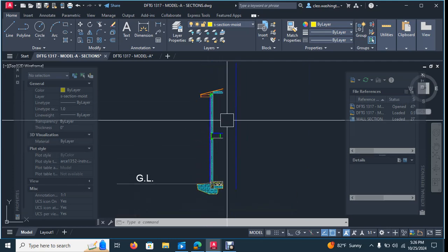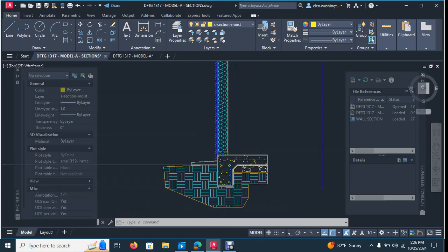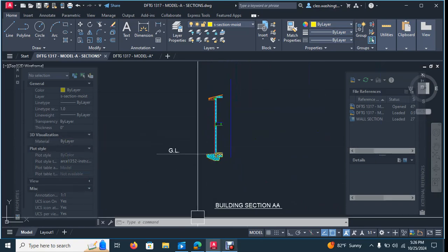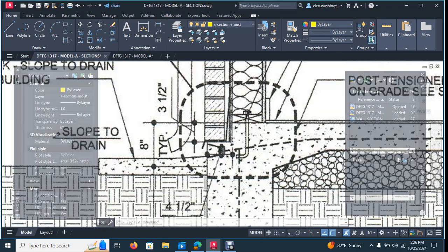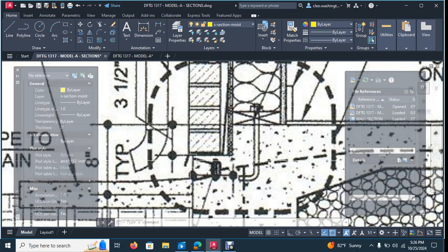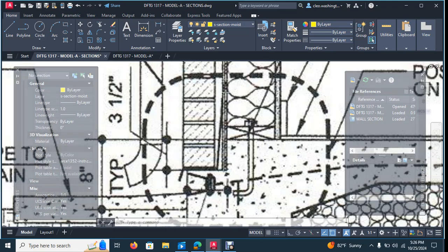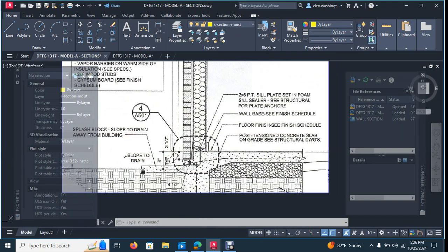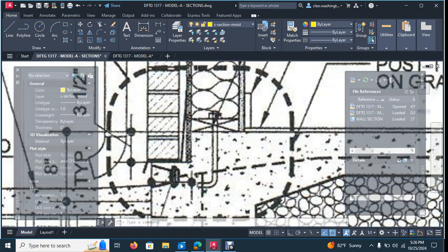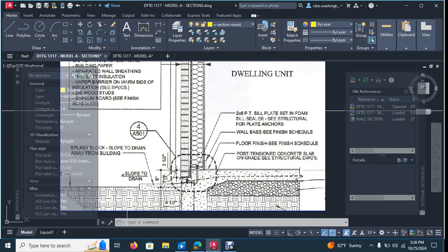So next I'll do one actually showing what the brick looks like. The brick is going to look just like this. You actually have a brick ledge where the brick would sit. And then the waterproofing or water vapor membrane goes up underneath the brick. And it has everything here laid out. We'll draw it out so you guys can actually see it.